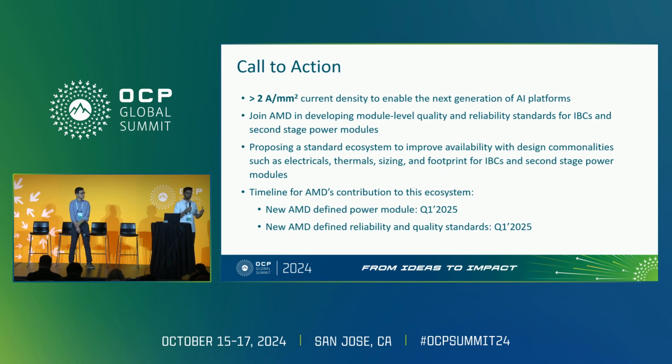For those, we'll use the proven non-TLVR, discrete inductor-based power modules. And wherever we feel a need for the rails I mentioned, mostly the core and the HBM, I think those are the perfect candidates to use the modules with improved magnetics, whether coupled inductors, TLVRs, and maybe high capacitance integration as well into the modules. And one more question, mounting: would these be top side and bottom side mounted on the board? So we are exploring all the options. So yes. Right, thank you.